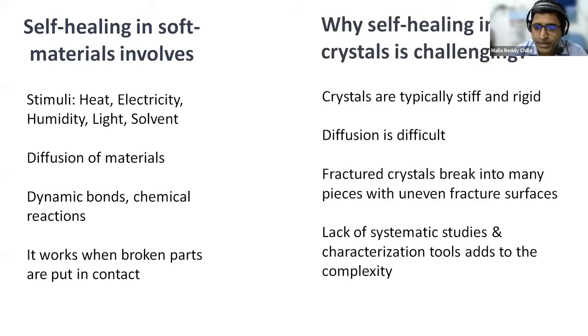But why is self-healing actually challenging in crystals? Because crystals are very stiff and rigid, and diffusion is also very difficult because these are densely packed materials, and they have very tight interactions. So you have a close packing. Because of that, diffusion is very difficult in molecular crystals. And then fractured crystals break into many pieces. Normally you don't have a very clean surface when you put them together, and since they're also rigid and solid, you cannot really close this gap properly. So that is another challenge.